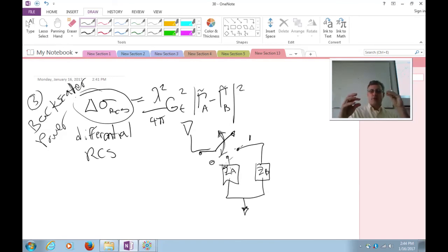We're figuring out how to get power from point A to point B and how to track it also in a reflective communication signal. Now that we can figure out how much power to get from point A to point B, we can track the circuit losses and the mismatch losses. And then we can figure out basically, okay, I got this much power. How much can this go end to end into this energy harvesting application? And thus, how much power will I have available? How much voltage will I have available if I want to hook a circuit to this antenna and do something with it in the far field?